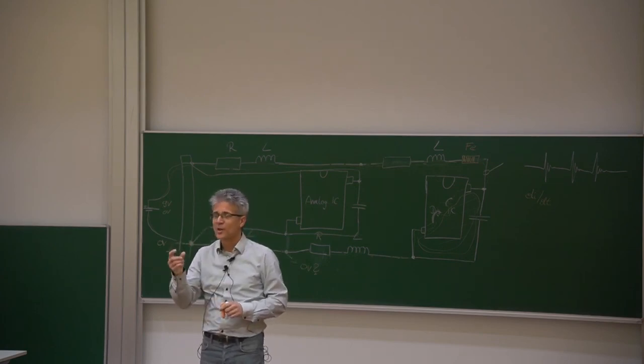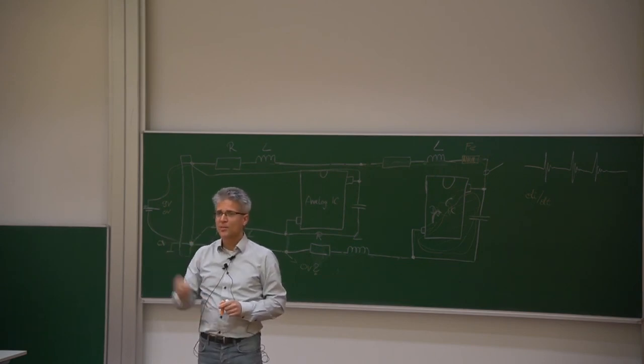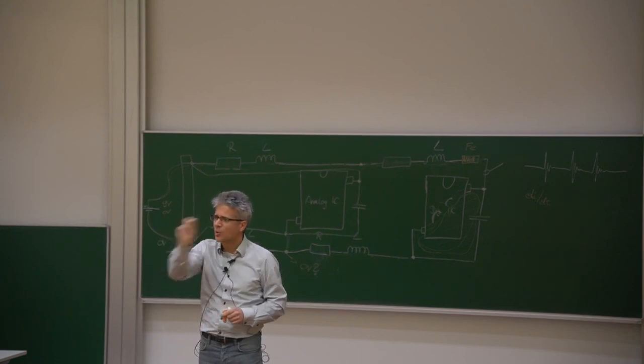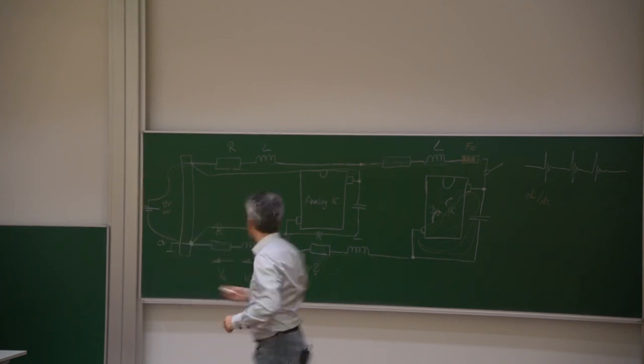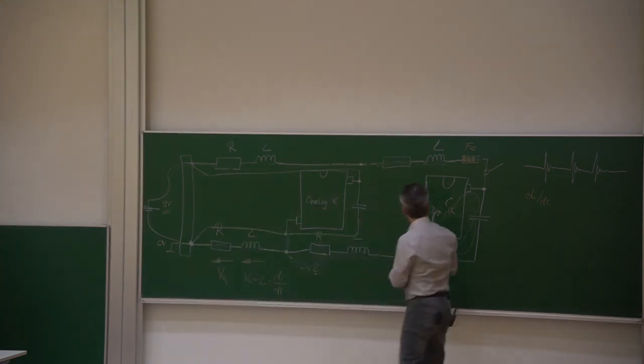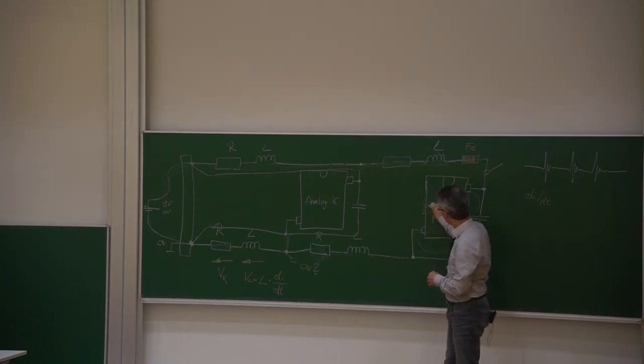Also the solution would be to place the VDD and ground pins as close together as possible and place them at the location where the smallest loop area, especially with the lead frame and the bond wires, will be possible. So very often we are placing VDD and ground here, then we have the lead frame and then bond wires, and then the loop area is that small compared to this one.